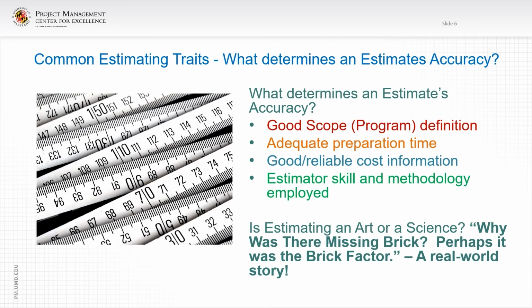Since 25,000 more brick was actually needed than estimated, the construction manager thought 25,000 brick were missing from the job site. But the error was in the calculation of the brick factor. That's why the brick masonry budget was showing a loss.